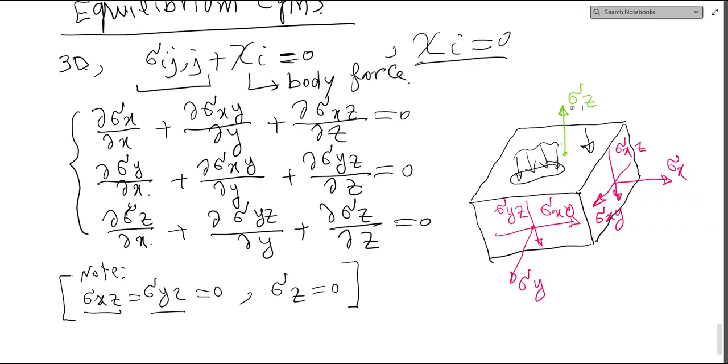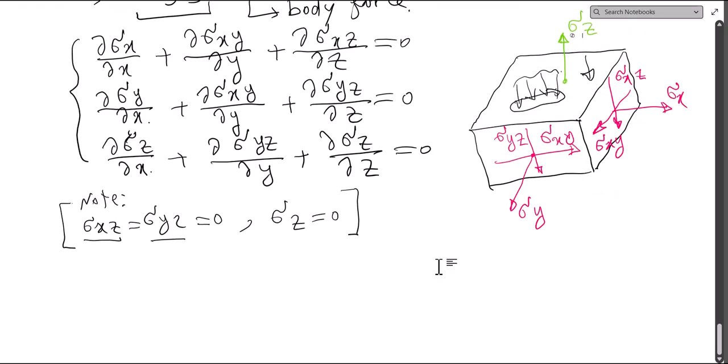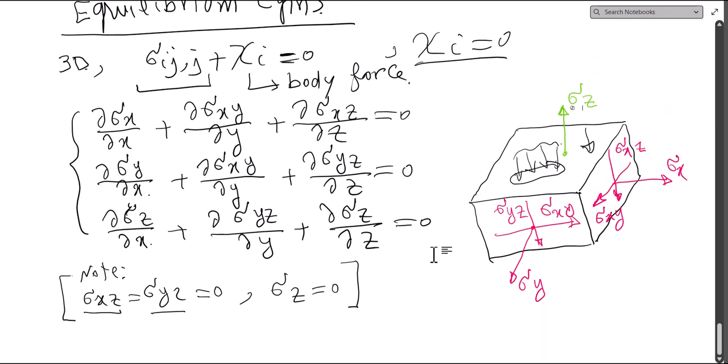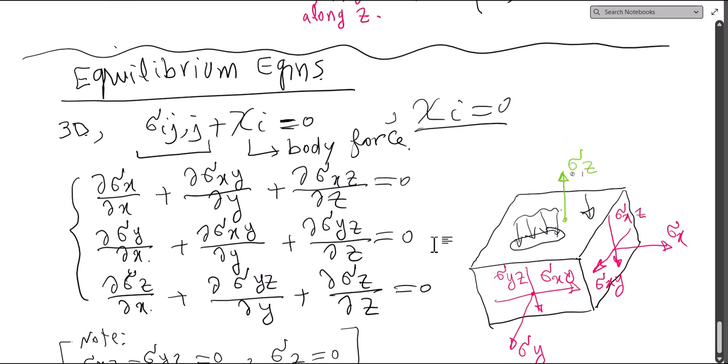And obviously at the bottom, on this plane, we have some traction, so we need that. And on the bottom plate, usually there is no load applied, so this sigma z should be 0. So these are the things that we see immediately from the requirement of the equilibrium equation, that we need to have some values with it.